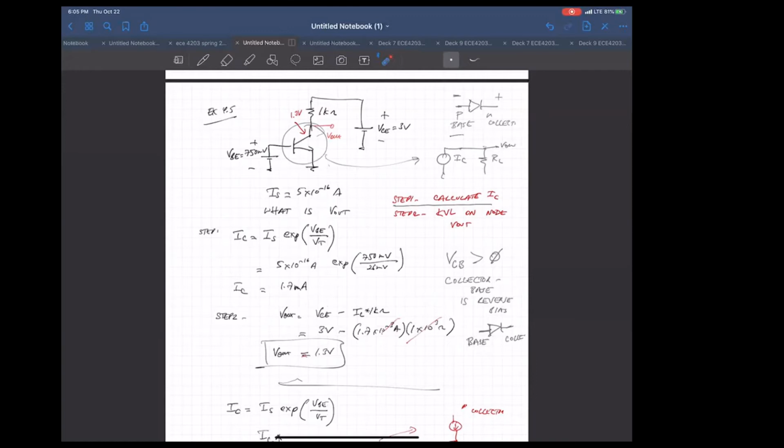By the way, I don't want to confuse you guys, but let me just state something. You'll see this a little bit later, in a couple of lectures. If you remember, because we had this VD on voltage, this collector could even be a little bit less than the base, and the diode would still be reverse biased, because it has to be below 1 VD on, which was typically 700-800 millivolts.